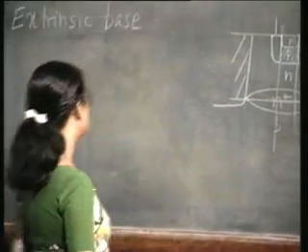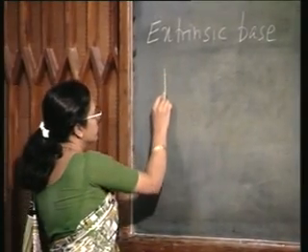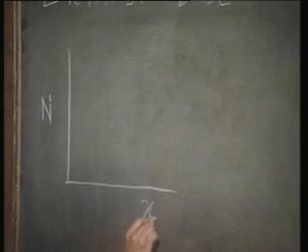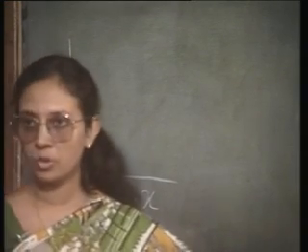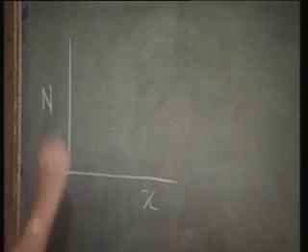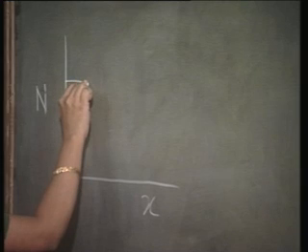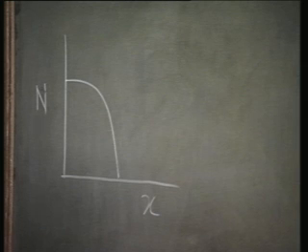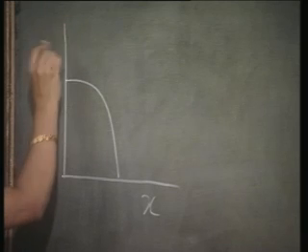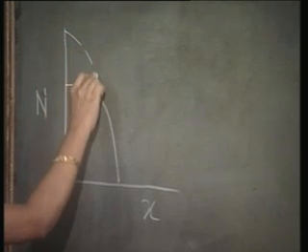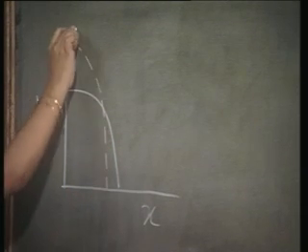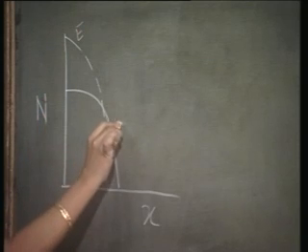How? Let us see. Suppose what I am trying to plot is the doping concentration with the distance. Now, let us say I use an implantation like this for the base region, an implantation profile like this for the base region. And let us say my emitter doping is going to be the dotted line for the emitter, the solid line is for the base, right.